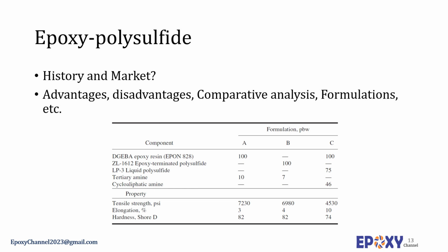The maximum service temperature is about 50 to 85 centigrade, depending on the epoxy concentration in the formulation. And the temperature resistance increases with the epoxy content of the system. Resistance to solvent, oil, and grease, and exterior weathering and aging is superior to that of most thermoplastic elastomers. A typical formulation has been presented for adhesive systems formulated with polysulfide as a modifier for a system where an epoxy-terminated polysulfide has been employed.